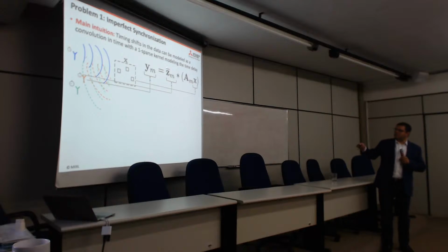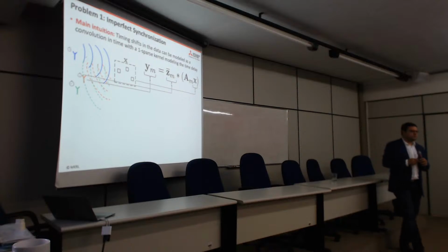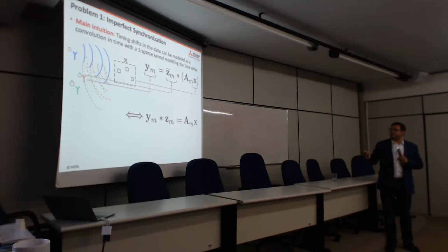Now, that problem is actually nonlinear because you have that unknown. This is something you don't know, right? It's a clock delay. So you'd like to recover this and this together. But that unknown is convolved with this signal, so it's multiplicatively involved with this unknown. So you have a nonlinear problem, but you can do tricks. One trick is to bring that unknown to the other side.